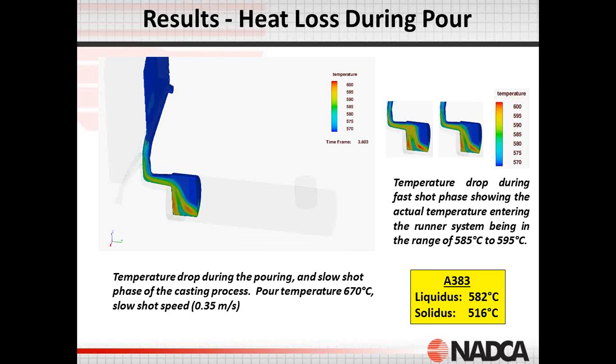So just from this, it is interesting to note that if we're getting cold flow defects in any kind of casting process, one thing we can pay attention to is to decrease the amount of time we pour into the shot sleeve, and even put thermocouples in the shot sleeve to measure what that temperature is, because it might be a lot colder than we might have expected.